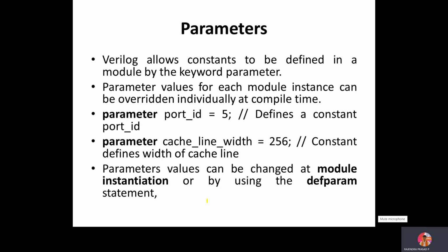Now I need to know how many bits this 5 will have in binary. Whether it is 2-bit data, no, it cannot be 2-bit data. It should be 3-bit data. So 5 is represented as 101, 4 as 100 and 6 as 110. When I'm comparing in Verilog, I am comparing bit by bit. So now the 5 value is 101, and one more 5 I am taking as 101.